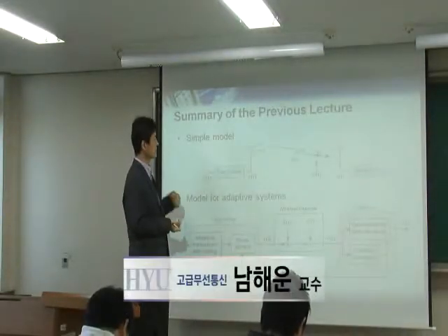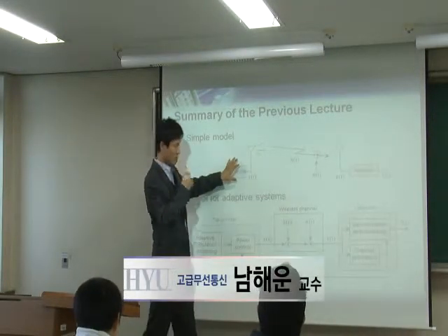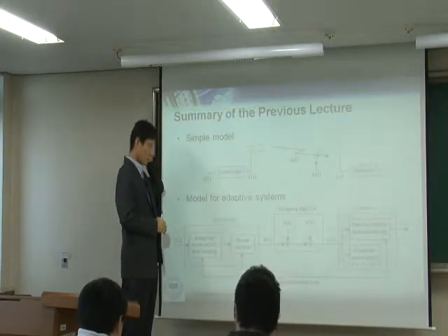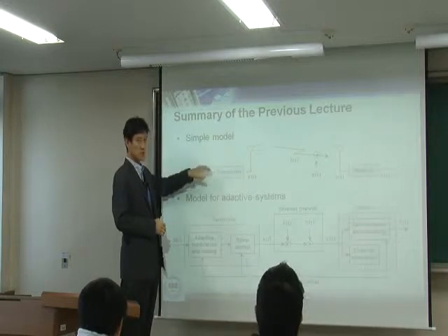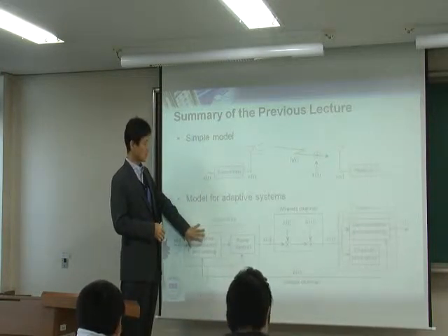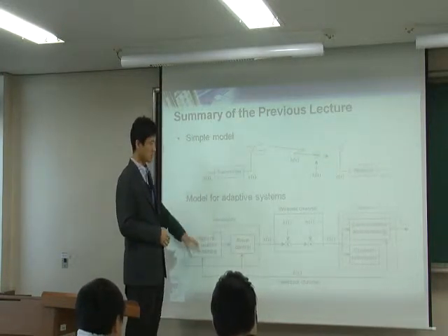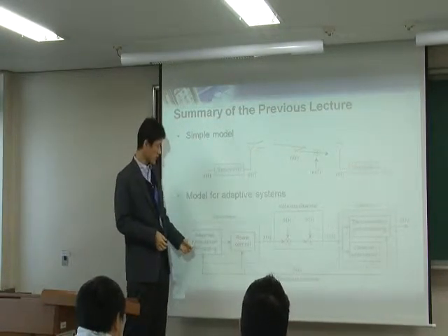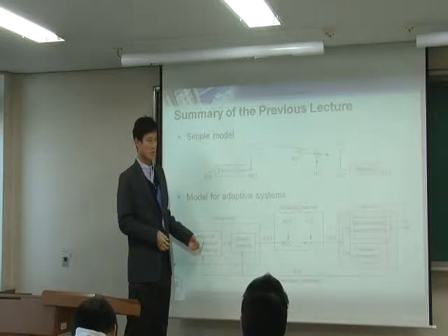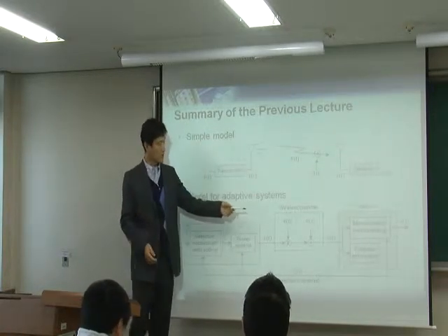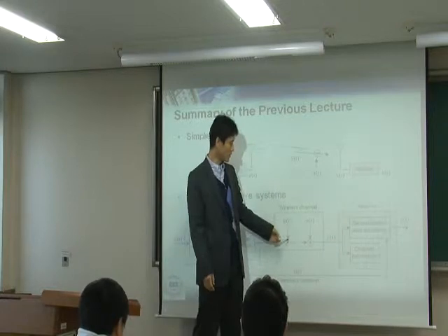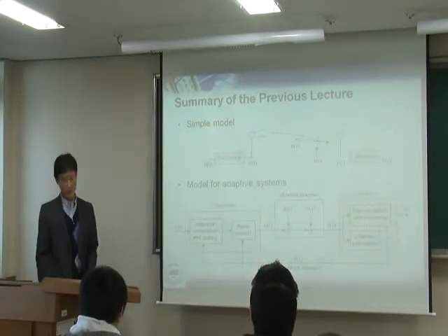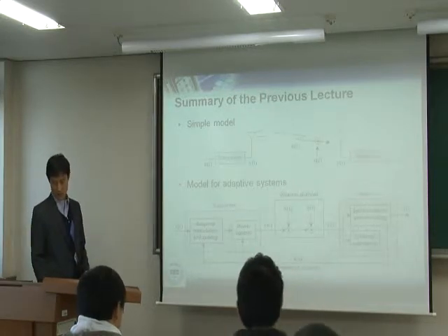First of all, we start from the simple model: one transmitter, one receiver, okay? And we look inside the transmitter and receiver, and we can model each one like this using the block diagram. Inside the transmitter, as you see here, we have a power control block. We also have a modulation encoding block. In the channel, we have a fading multiplied with the channel and also the noise, which is added. And in the receiver, we do the demodulation and decoding, and also the channel estimation.